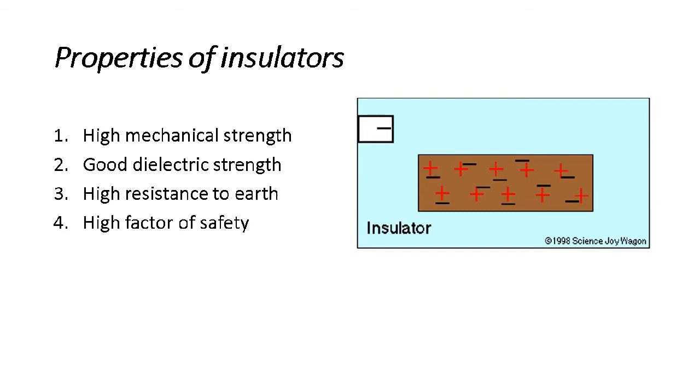Okay, now flashover strength is not in our hand, but puncture voltage is in our hand, so we can control it by designing some kind of insulator in such a way that puncture does not happen. Okay, so this is all about the factor of safety.